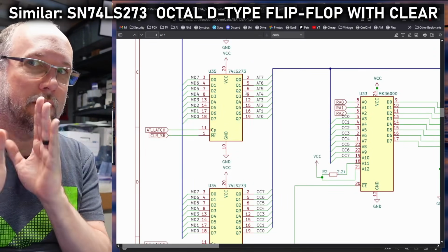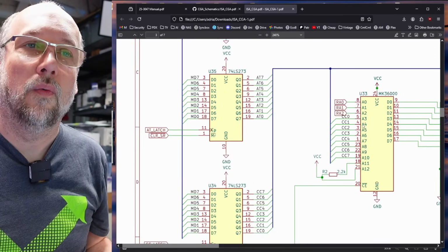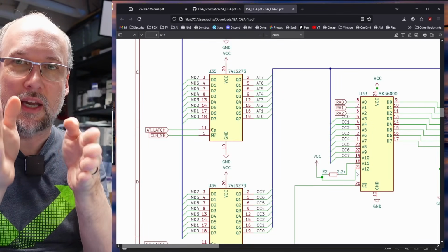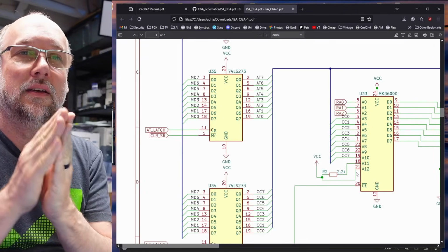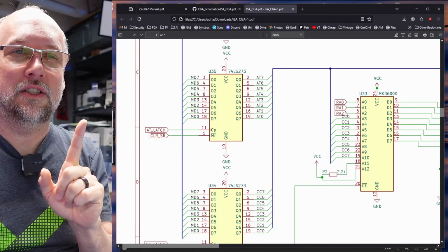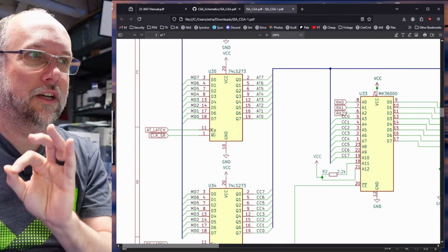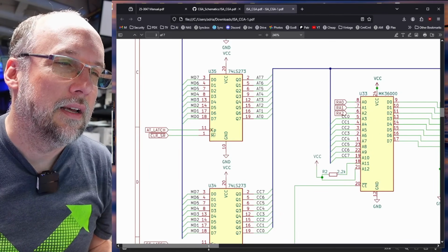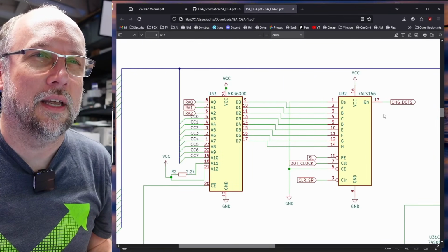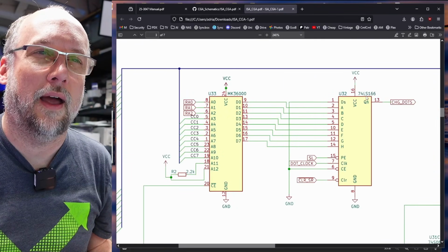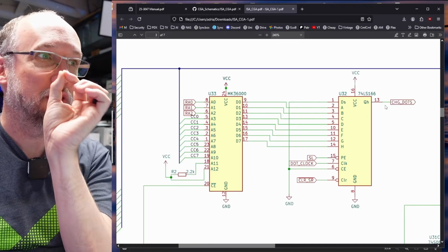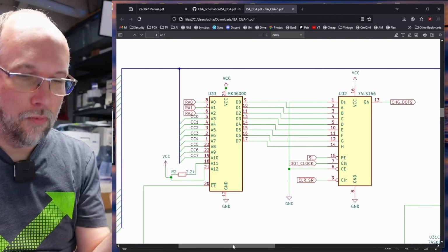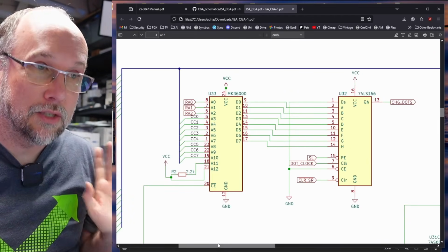It's the odd and even byte, it's getting split, and then one of them needs to go to this character ROM chip. So as that particular memory location is being read by the CRTC, the character generator, based on these lines here that come from the CRTC, is generating the specific row of pixels for the character being generated, and those are going to come out of this and go into a shift register, which is this LS166, and that gets turned into actual pixels that get written to the screen. We know from our notes here that whatever's happening on this card to do that is working as well.